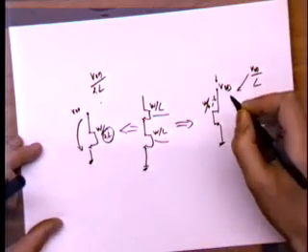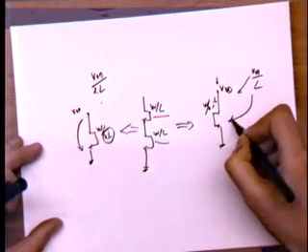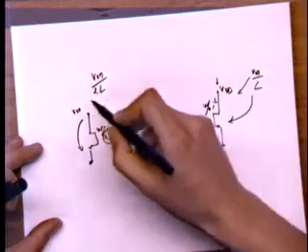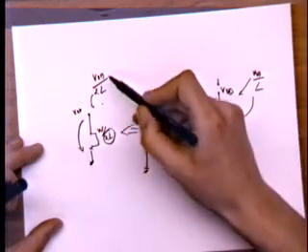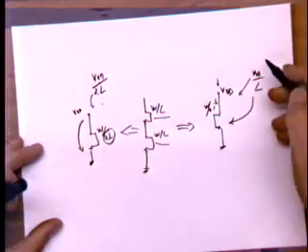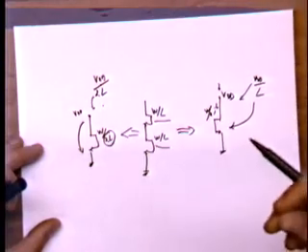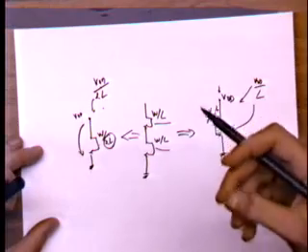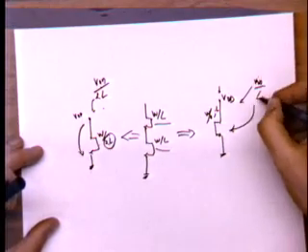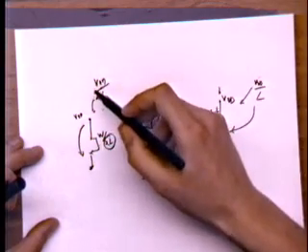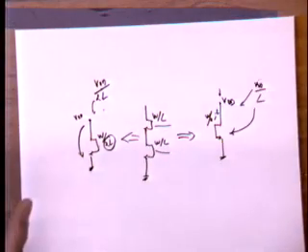So you can see from this that this guy operates at a higher electric field than the guy on the left. And therefore, it's going to be more velocity saturated than the guy on the left, okay? So because we know that velocity saturation degrades the on current, we know that the guy on the right is slower than the guy on the left. Okay, does anyone follow this?